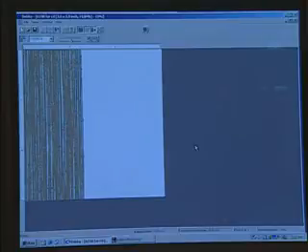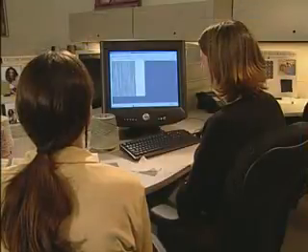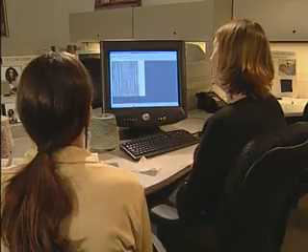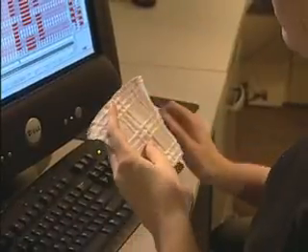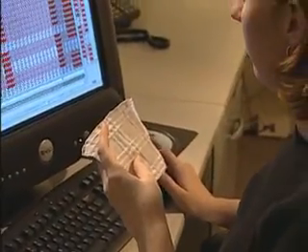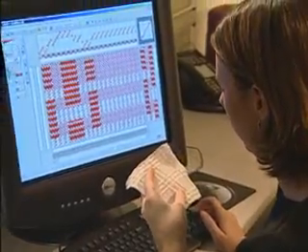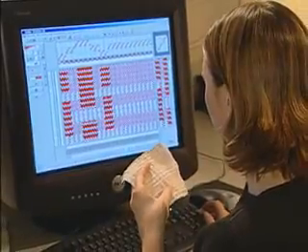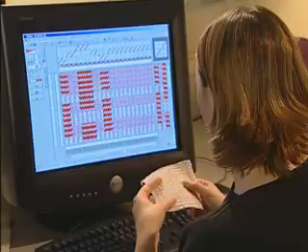Adjustments to the weave or to the yarns can be made at this time before the design is transferred to the loom. Once the information has been entered and the simulation has been approved, the file can be sent electronically to the loom. Once the project reaches the weave room, a sample called a head end or strike-off is woven. Usually a few yards are woven and sent back to the designer to approve or make any final adjustments. Once the head end is approved, the fabric is woven.